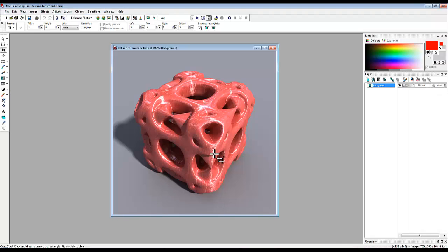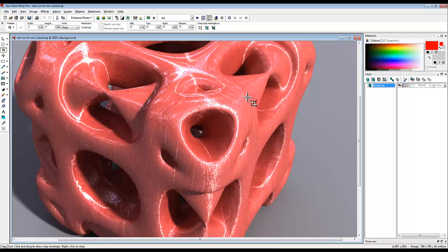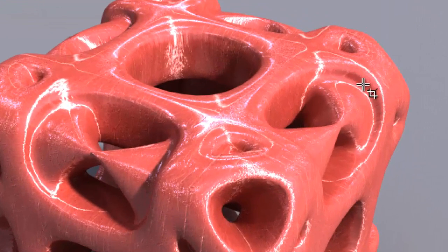What I'll do is have a look at this in Paint Shop Pro. So trouble areas, if you'd used Object Cubic with non-tiling textures, this corner for example, and this corner here, obvious trouble points as I pointed out before. Other areas, oops, I need to slide this around, is here, where you see this got a slightly stretched appearance from the spherical mapping, and inside here, but otherwise you would have had a situation with Cubic where it would have had one face here, another face on this side of the inner cut circle, and another face here. So you'd have had a transition zone here which wouldn't match up very well, and here and here.